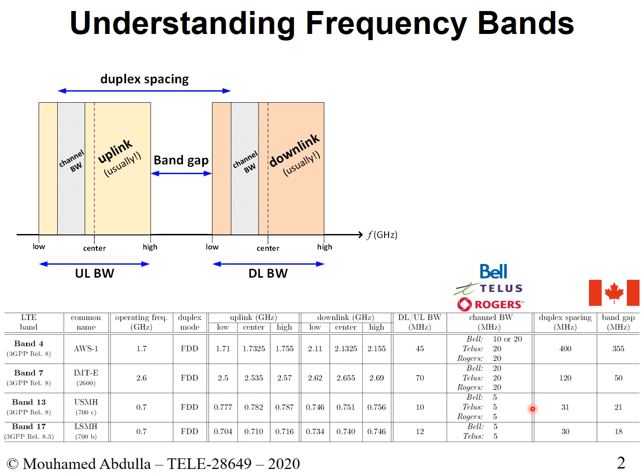The other thing that is important to know here is the duplex spacing. This is very important. Basically, because we said that in this region, you won't use all of it. You'll just be using a slice when you make a phone call or when you check your email on your phone. The two slices, you want to have a gap between them, right? So imagine if your slice here was closer, this is okay, you're still far away, but you want this gap to be farther away from each other. The larger this duplex spacing is, the better it is. The less the potential of crosstalk. There won't be collision between transmitting and receiving. Right? So you want this to be large.